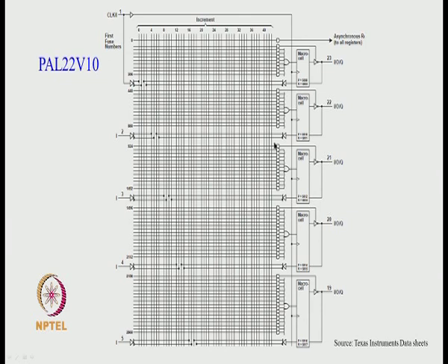So that is the device, and similarly you have the tri-state gate enabled by a control product term. But in addition to this, you should note that at the top is an AND gate which can be a kind of decoding of all the 20 inputs or their complements, and that goes to the asynchronous reset of the register. So you can, in principle, give a reset signal here, and you can reset all the flip flops at power on, and it need not be a simple reset. It can be a combination of conditions, and depending on those conditions you can reset it.